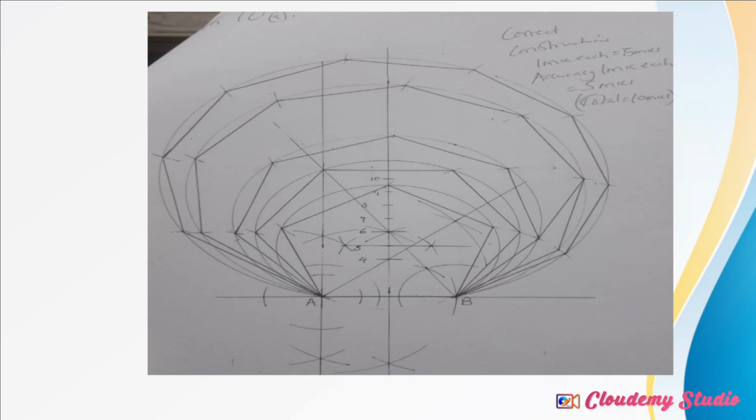For you to bisect, you stand at point A and make an arc with a reasonable radius that cuts the perpendicular line and the horizontal line. Then you join the two arcs to get the 45 degree angle. You can extend that 45 degree line because it has to pass through the perpendicular bisector to the other side. Then you come to point B to construct the angle of 60 degrees by using a reasonable radius.